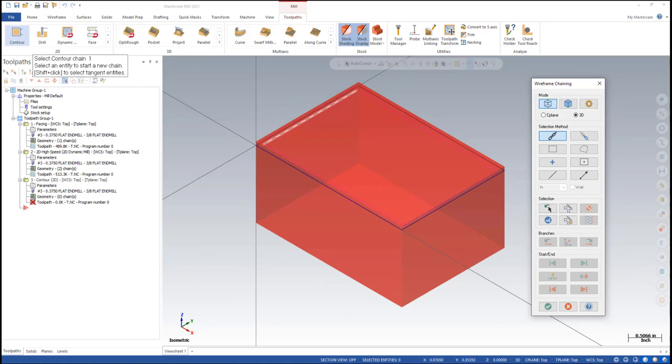And whichever line you choose is going to be the line that it starts on. And if you take that line segment, so say we focus on this line segment here, if you divide that in half, like at this point, if you click anywhere on this half of the line, it's going to position the beginning of that line segment at this side, and it's going to send it the other direction. It's going to send it away. So if I click on this half, it's going to place the contour beginning here and sending it that way. See, the arrow is here, and it's sending it that way.